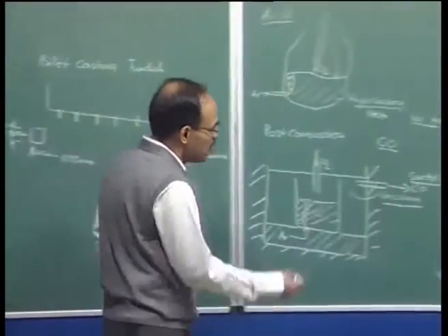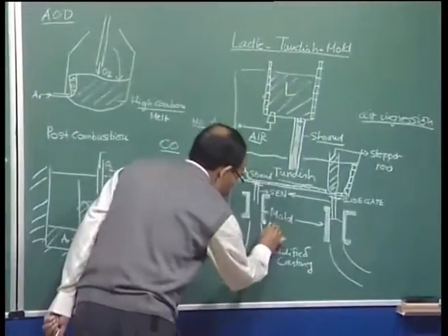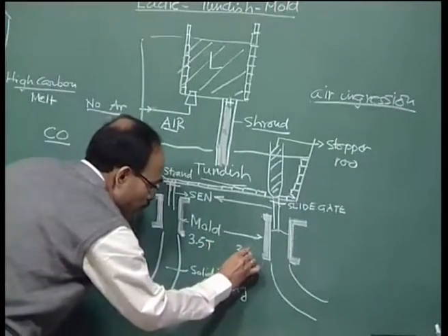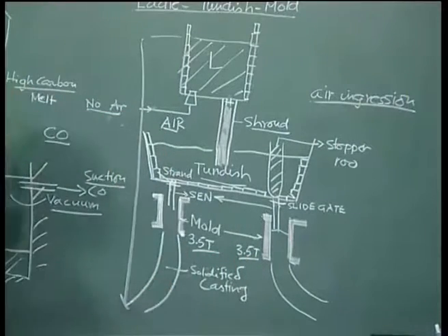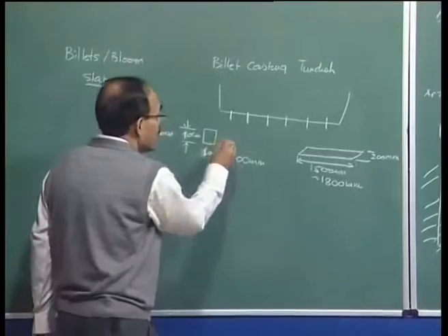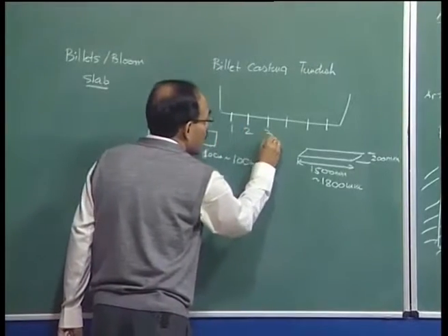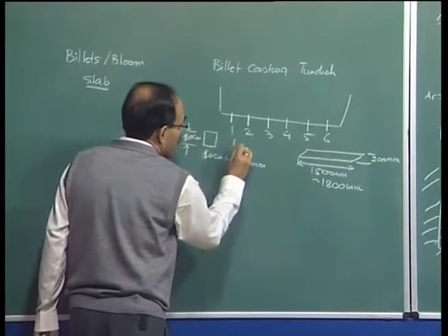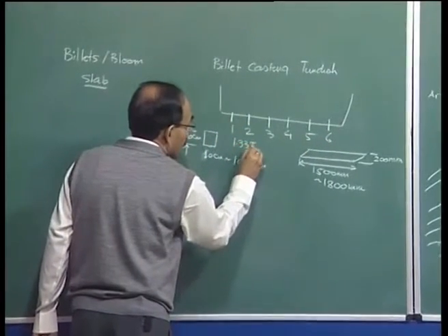So, for example, in industry you can see that we can have 3.5 tons per minute. That is the rate of casting in a conventional steel plant, steel mill. So, we are casting through two strands about 7 tons, and if the same plant were producing billet, it would be using strands number 1, 2, 3, 4, 5, 6, and in each of which maybe we will have casting something like 1.33 tons per minute.